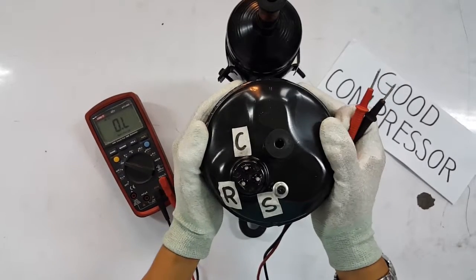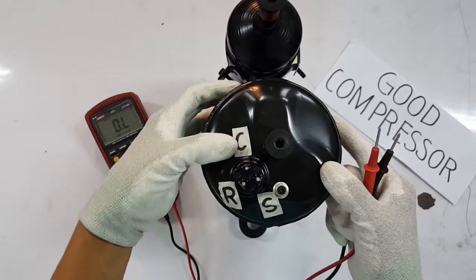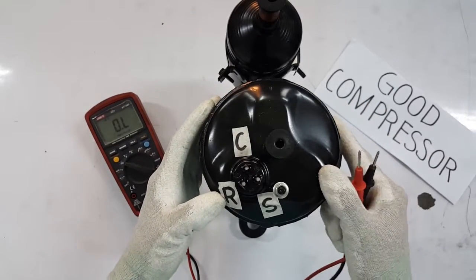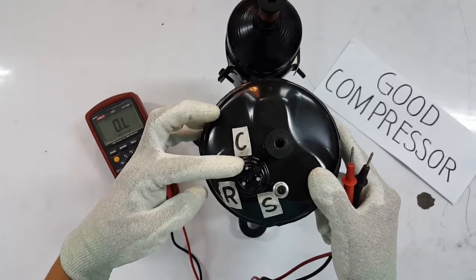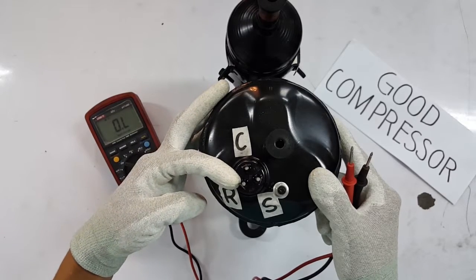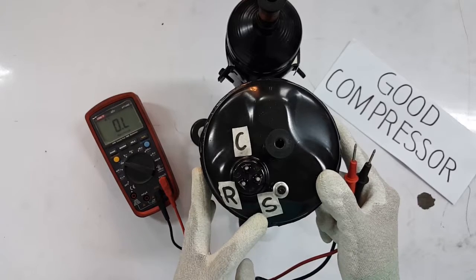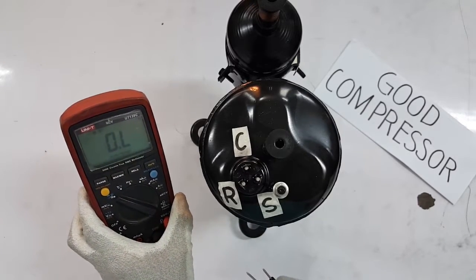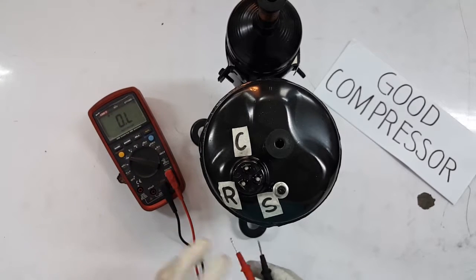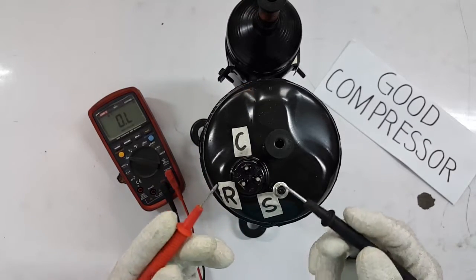Alright, so this is an example of a good motor compressor. Then we have C for common, R for running, and S for starting. So this is the terminal for C or common, terminal for running or R, and terminal for S or starting. Then we will use a DMM, a digital multimeter selected to resistance measurement. Regardless of which lead we use, the terminals are interchangeable.